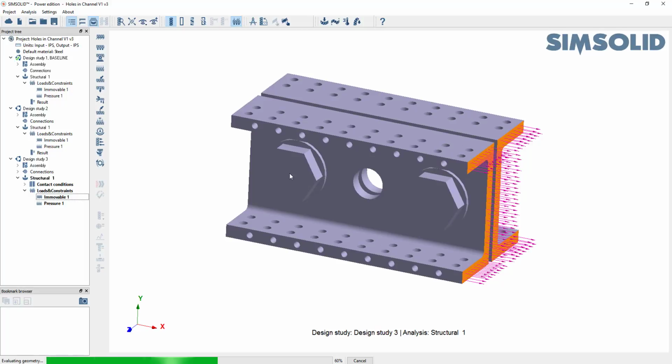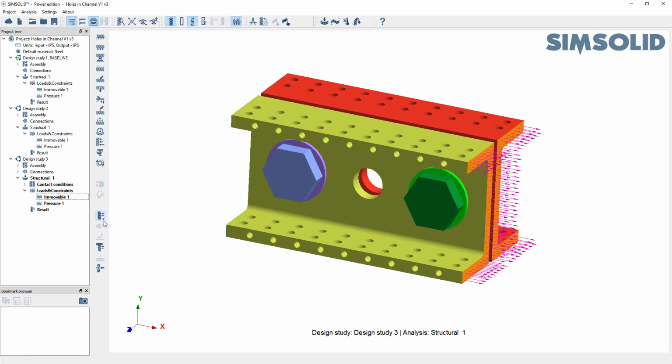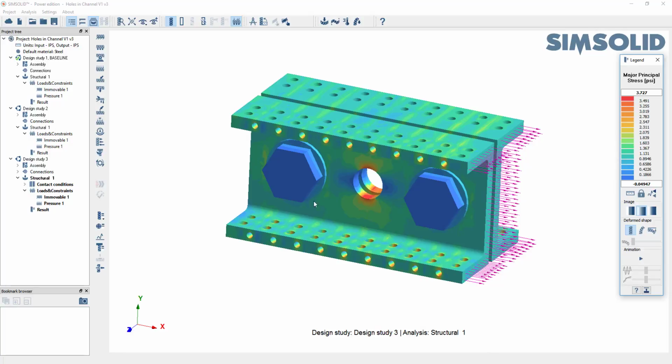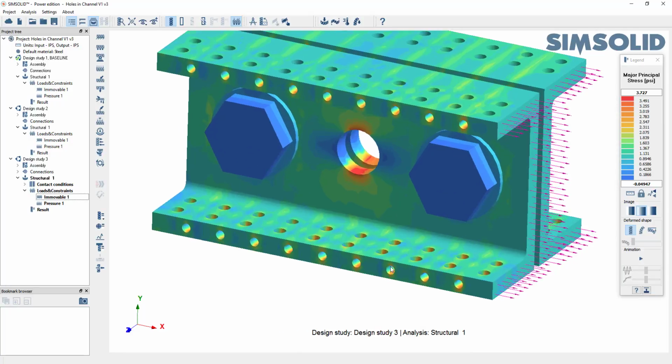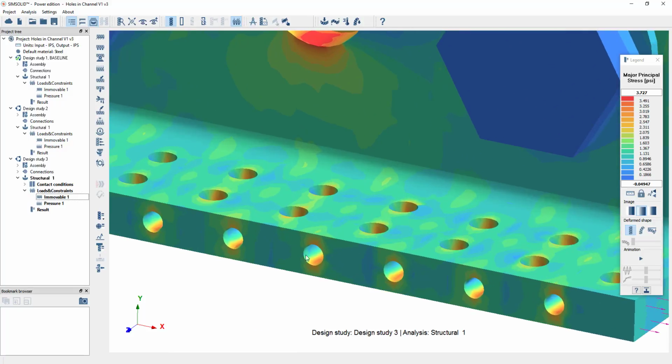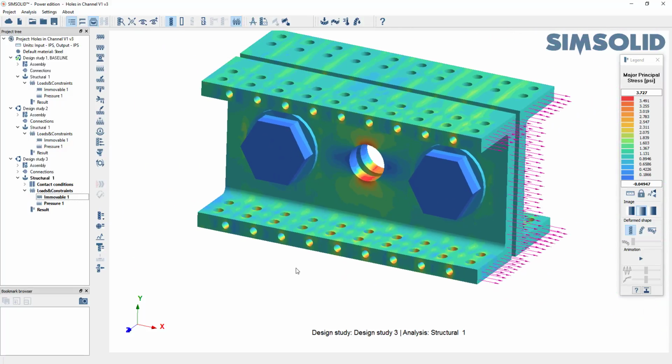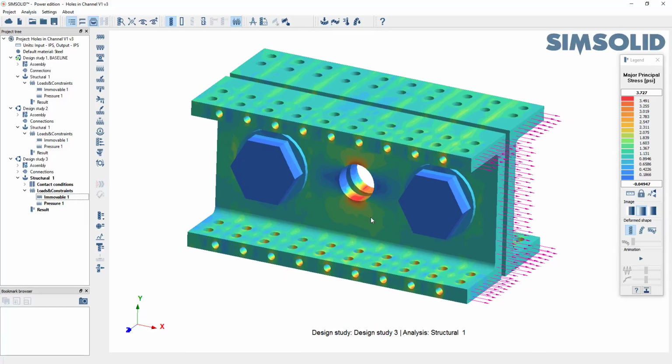And again, even though I've done very little to set up the runs, I'm getting a detailed stress study done on the original CAD geometry without any local remeshing or local manipulation of the geometry. It's all done with the default conditions, all done automatically. So here are our stresses on this model, and you can see we capture all this nice stress detail up in the holes here, here, down there, all with default solutions, all done very rapidly, all direct from CAD.